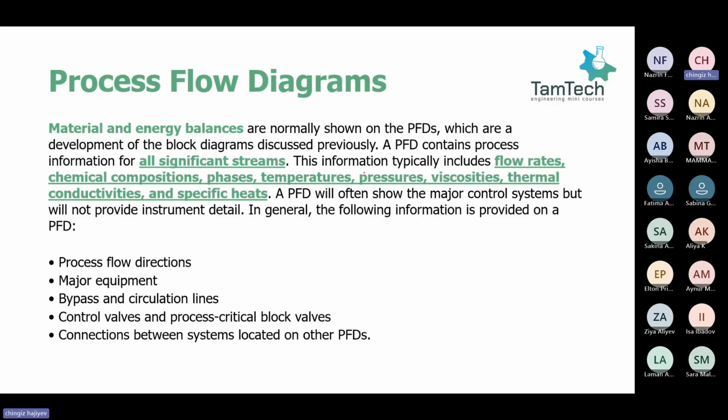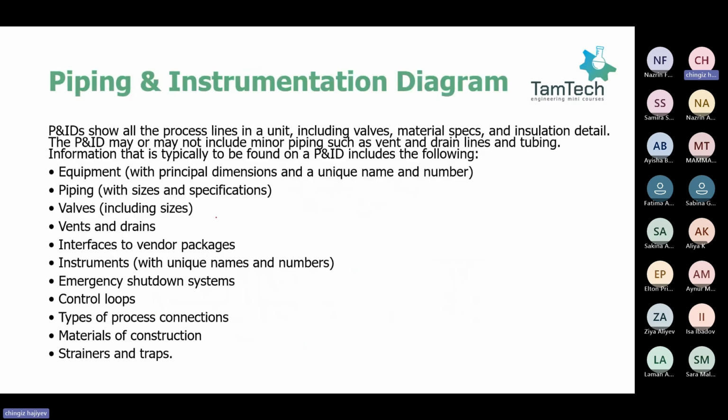Last words about PFD is that we typically need to include flow rates, chemical compositions, phases, temperature, pressure, viscosity, thermal conductivity, specific heat, anything about the material inside our piping and our equipment. Then the most detailed diagram is piping and instrumentation diagram.